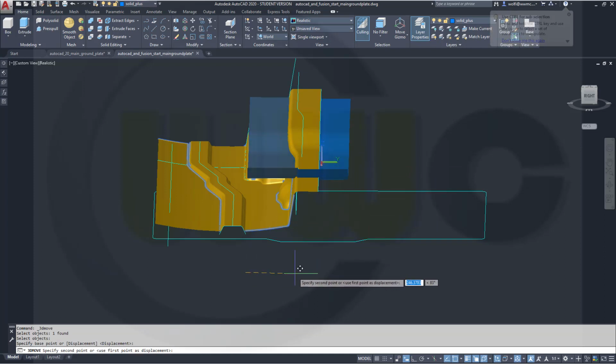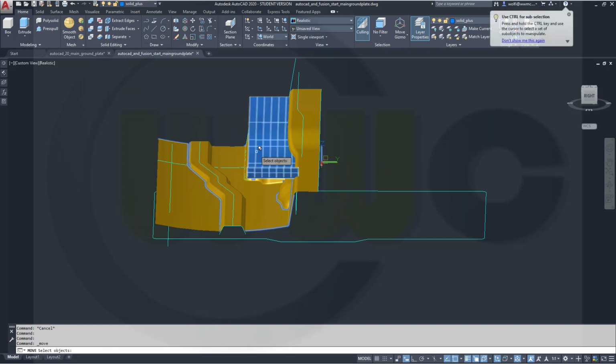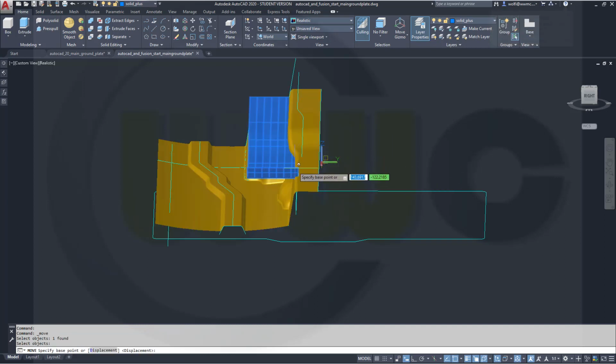In that direction, so it would be nice to go with a trace, but therefore I need a point. Okay, this one, right click, select this point right here, maybe, doesn't really matter, some point which I can snap, this one, yeah, in that direction, make it 100.